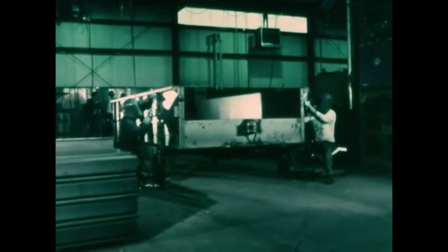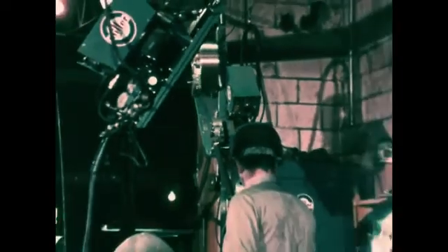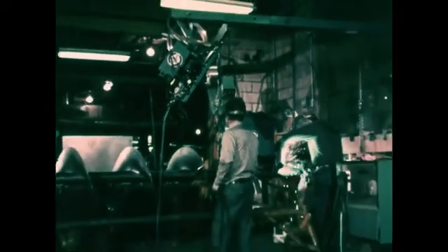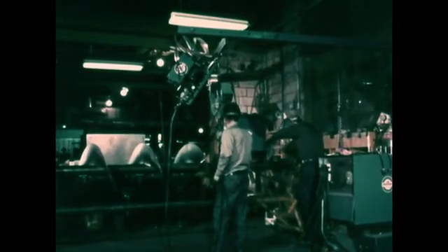The out-of-position welds made possible by the short-circuiting method permit operators to move rapidly along an entire workpiece, changing smoothly from horizontal or vertical to overhead welds with ease. Large augers of this type may be welded by 2 or more operators working side by side. While skill is obviously required to lay in efficient welds along curving lines, the persistent dependability of the process ensures a very high level of approved weld joints.